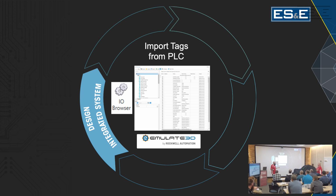Hayden, what would I tie my distance tag to? Well, if it's a servo motor, wouldn't it be the current position? Yeah, so you'll use your position information. So it links whatever I'm doing in Emulate3D with a tag inside the PLC that can give me that feedback. Exactly. We're going to use the .ActualPosition tag for the servo axis, and we'll use that to tell us where our position needs to be.